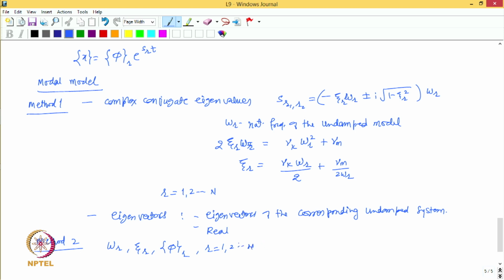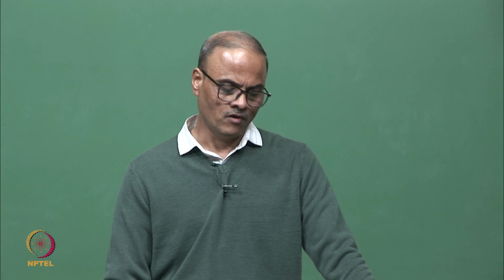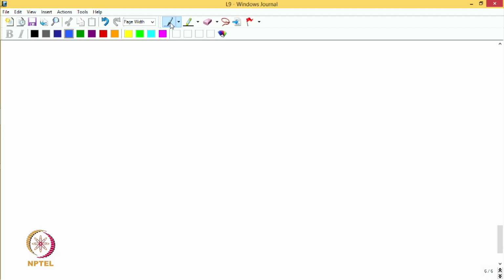These quantities together make up the modal model, and if these are given, the dynamics of the system get defined. We can determine the free vibration solution. So, what is the free vibration response?